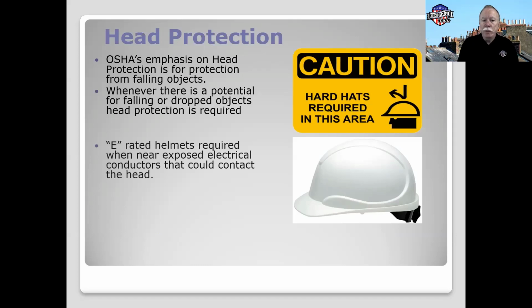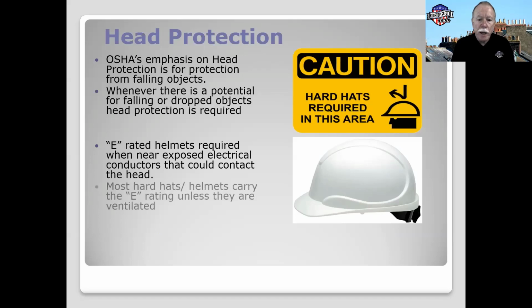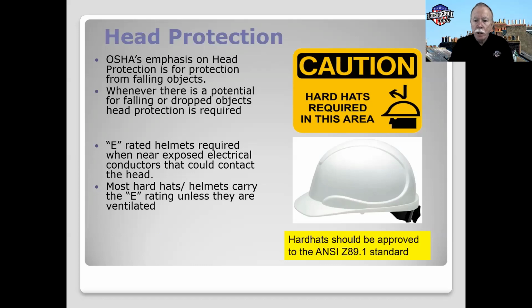If you're working around exposed electrical conductors, then your hard hat needs to be E-rated, meaning it protects against electrical hazards. Most hard hats do carry the E rating unless they're ventilated. Hard hat should be approved to the ANSI Z89.1 standard.